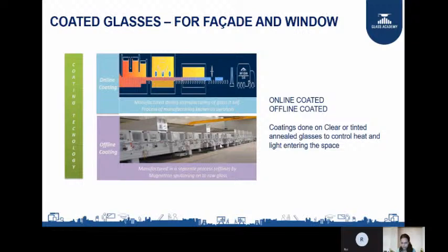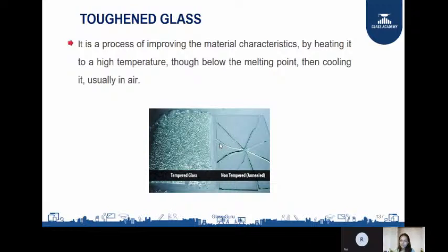Now the end result of this process will be a glass. You can see there is a little greenness in the glass, right? It is because of the iron material. The sand which we use to manufacture the glass has some defect, we can say. So if you want to lower that greenness in the glass, you have to use proper sand which has a low amount of iron, right?